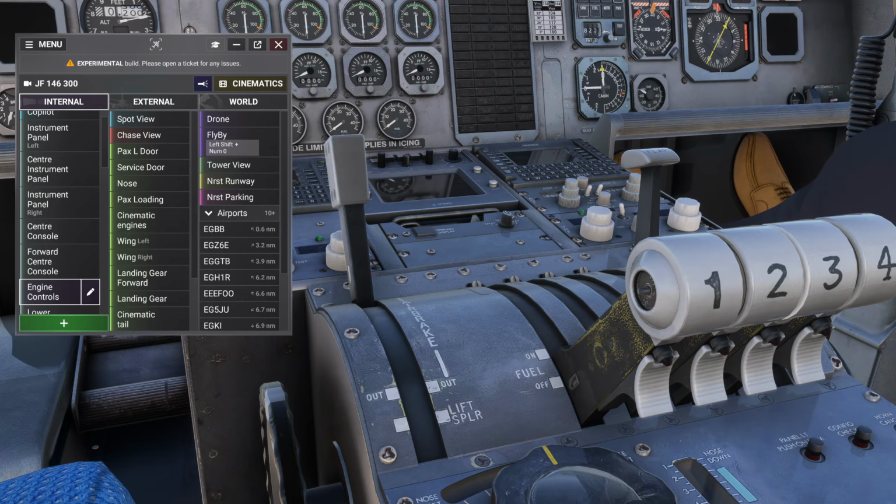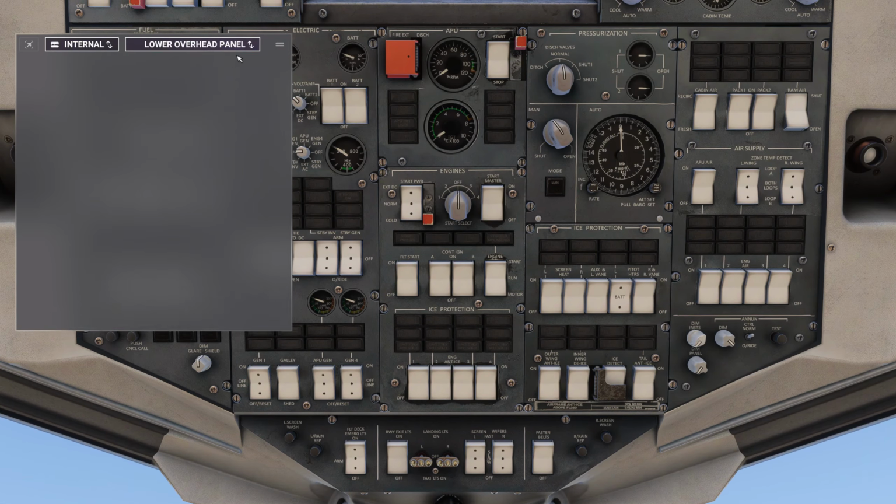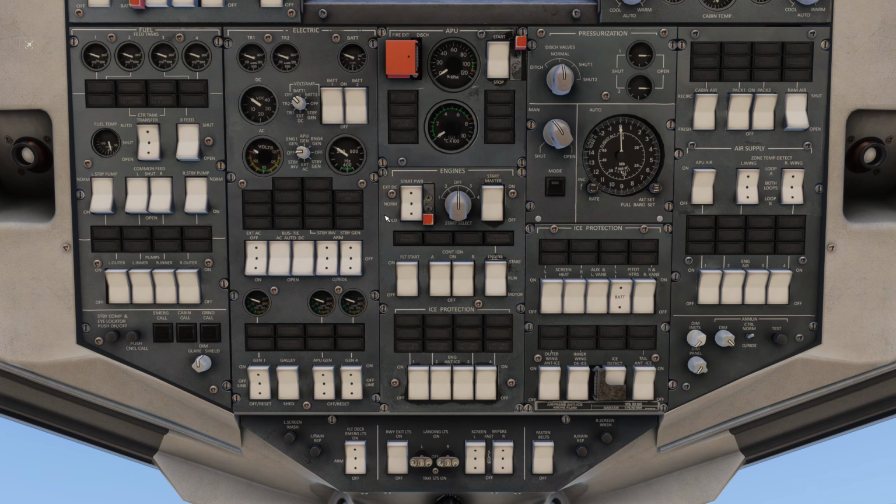Can you make it shorter? So to the point, not a lot of talk about the thing. So let's continue with the next item, please. Got it. I'll keep it concise. Next, let's turn on battery 1 and 2 and check that the battery voltage is around 28 volts. Let me know once that's done and we'll move on. Okay, you don't have to say that, let me know when it's done. I will say it to you. So, okay. Perfect. Sounds good. I'll just keep it straightforward and you can let me know when you're ready to move on. Let's keep going step by step.